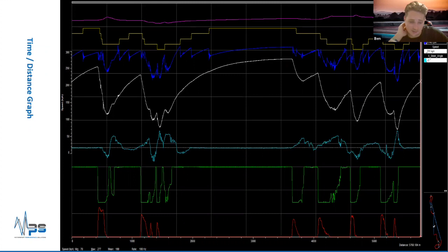Some things are obvious. For steering angle, you might only be able to go half a turn lock to lock, so minus 180 degrees to plus 180 degrees. Throttle can only go from 0 to 100, but for speed, for example, or brake pressure, you have to go through your data and see what limits you're working within.